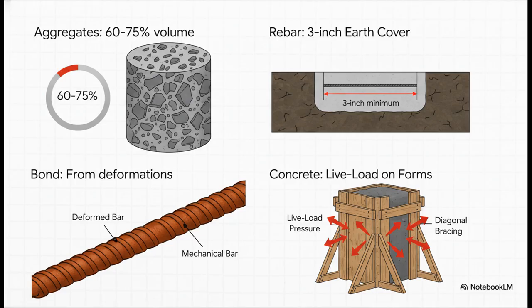And finally, never forget that wet concrete is a massive live load. If your forms are improperly braced, the lateral pressure from that wet concrete will cause deadly blowouts and collapses.